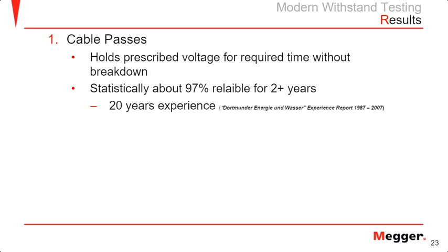So results, whenever you are doing a VLF test, at the end, if it holds the prescribed voltage for between 30 to 60 minutes, typically if it survives for the next 60 minutes, then statistically it's about 97% reliable for the next 2+ years. And I'm just not pulling this number out of anywhere.